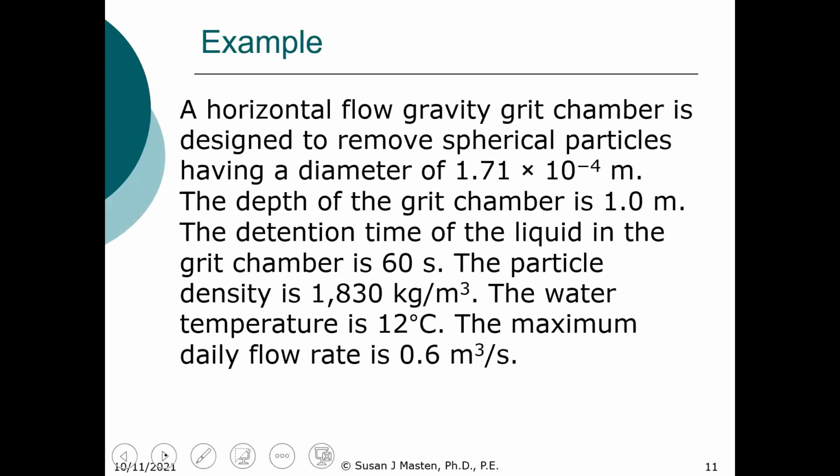So what I would like to do today is work through this problem with a grit chamber. Okay. So we have a horizontal flow gravity grit chamber. It's designed to remove spherical particles having a diameter of 1.71 times 10 to the minus 4 meters, so about 170 microns.